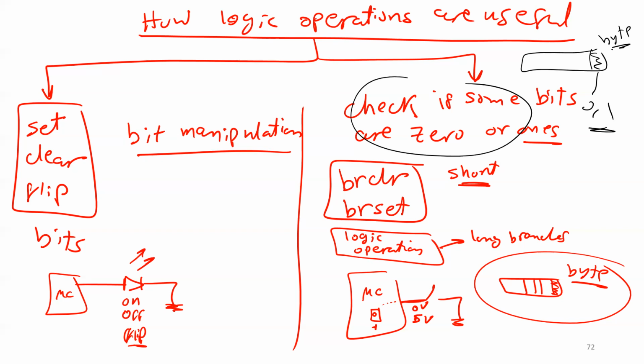Even if you are interested in only one bit, you have to read the whole byte. Once I get a byte, I'm going to check this bit, because I care about this switch. As I'm going to explain in chapter 3, as you see in this picture, every switch is connected internally to one bit. In the microcontroller we have an external pin.